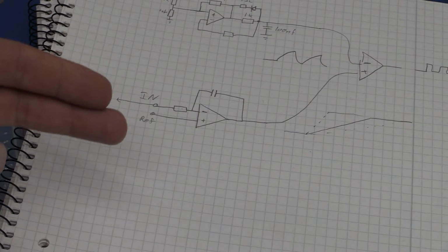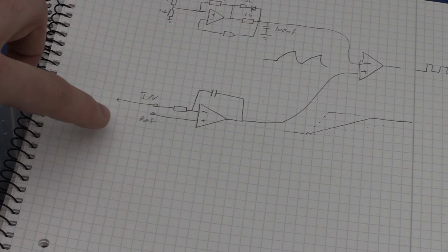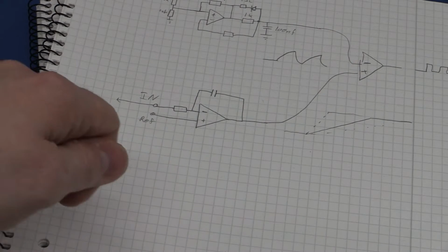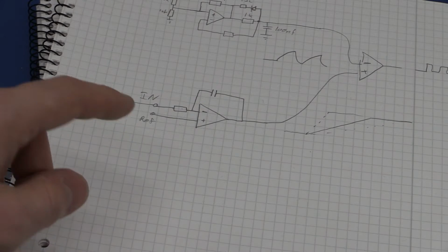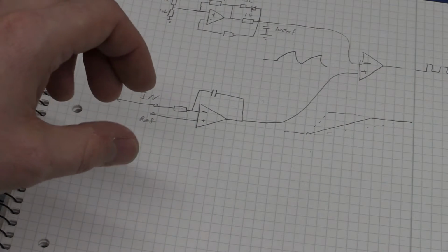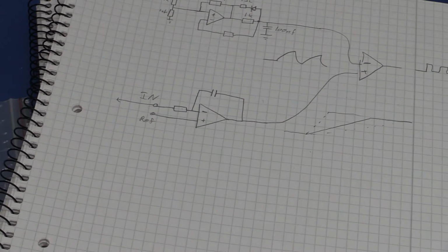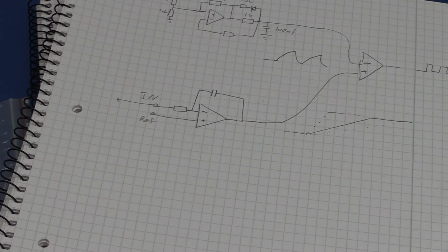So select an inductor and a capacitor and the sense resistor, and then set the reference current. The reference current can be a potentiometer, so it's adjustable. The only thing to consider is that the current should be within the range of the conduction of the inductor. So you select your inductor according to the switching frequency and the current.